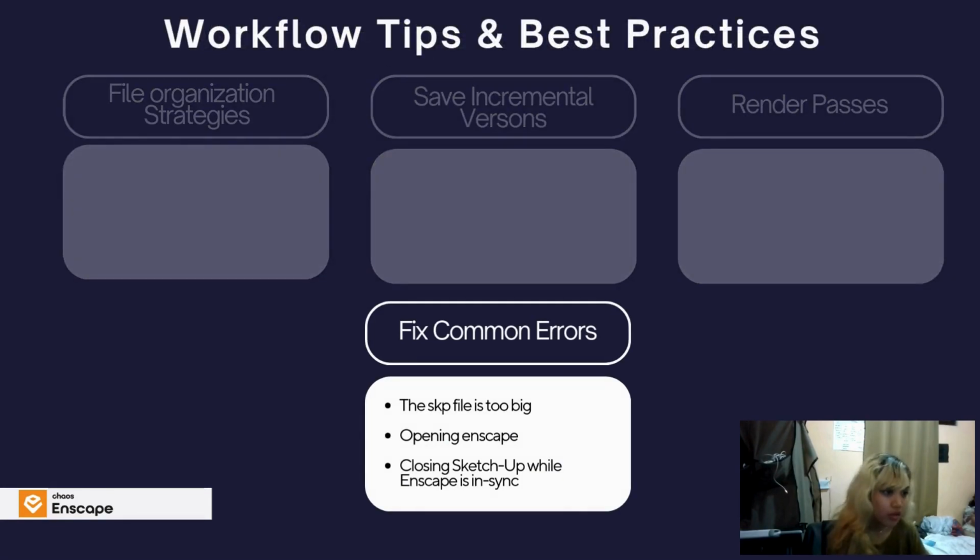The first error, and the most common one that you might encounter, is your laptop crashing or SketchUp closing automatically when it just opened. In layman's terms, it's called bug splat. It's because your SKP file is too big and your laptop is having a hard time processing and opening it. The best solution is to turn off layers that are not yet important to your scene or turning off profiles.